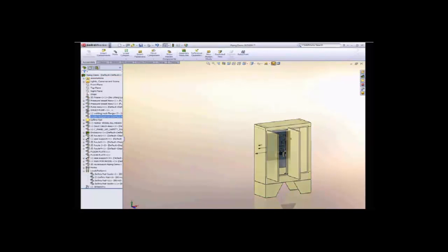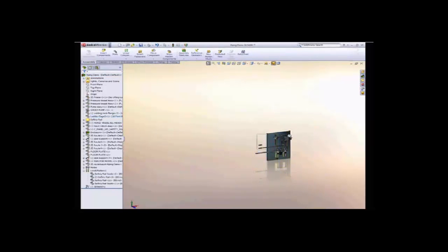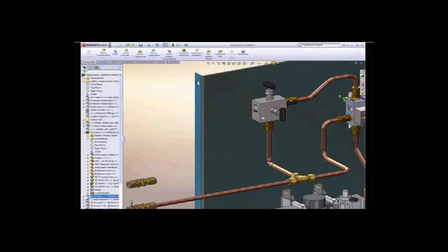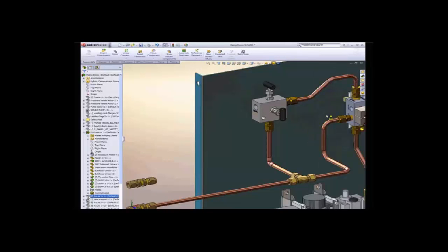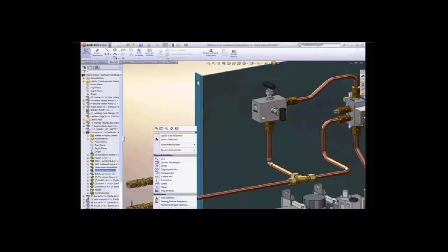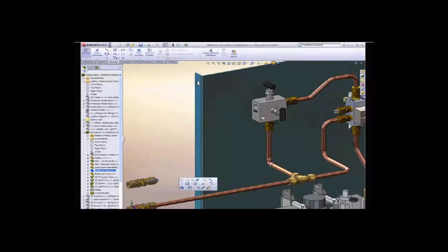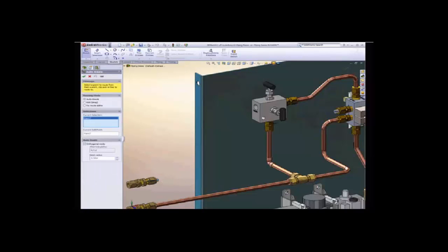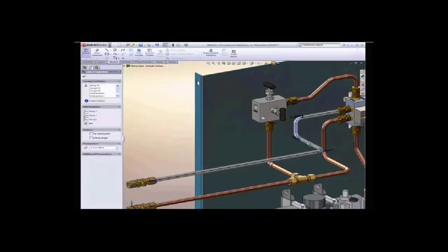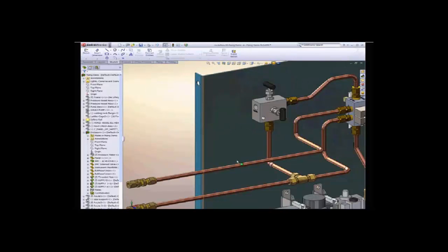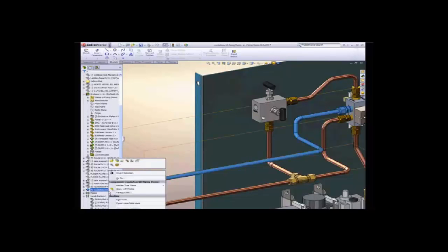Now, if we take a look inside, we'll switch gears and start looking at tubing a little bit. And you can see that in the same program interface you have the ability to pull in different fittings for the copper tubing industry. We can bring those tube fittings in, and we can add pieces to the route. And then of course just connect those 2 pieces with an auto route, and just as we did a minute ago with the piping, the tubing also does basically the same thing.